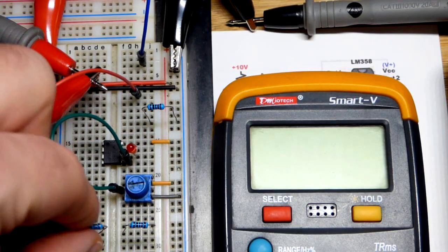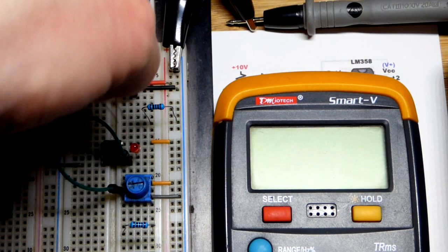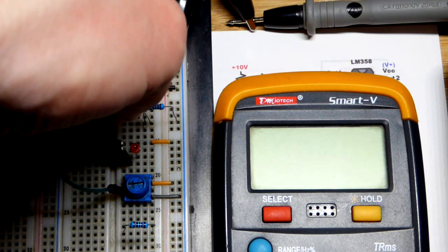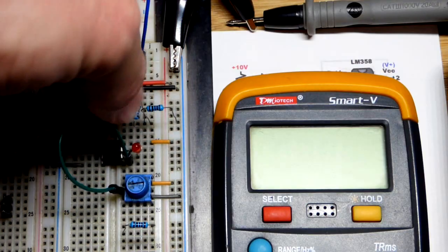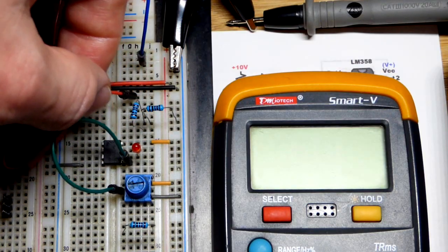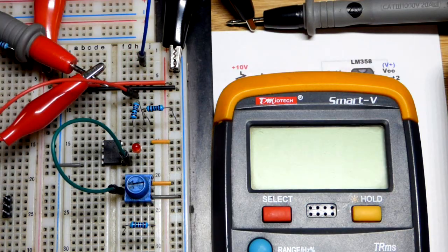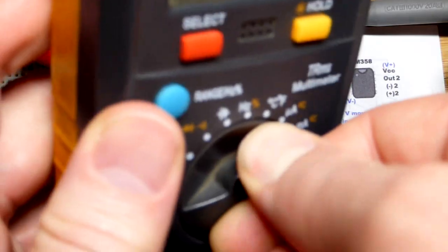So now, earlier I said that if you double the resistance, so we're going to make this 2,000 ohms of resistance by putting another 1K resistor in series with the one that we had before. So again, I'm going to be careful that, well, first I'll set the meter to measure milliamps of current, and then I'll be careful.